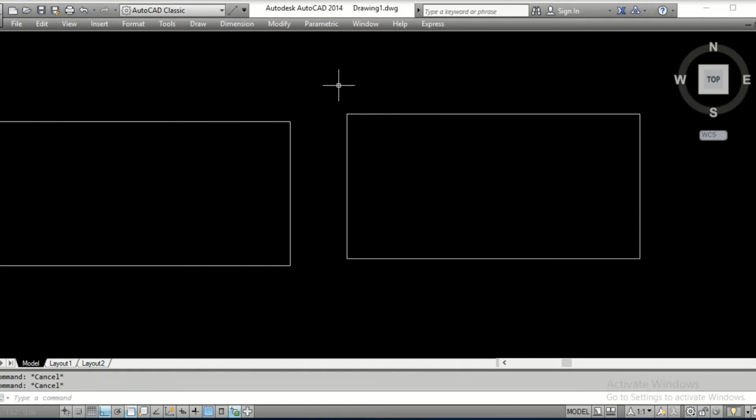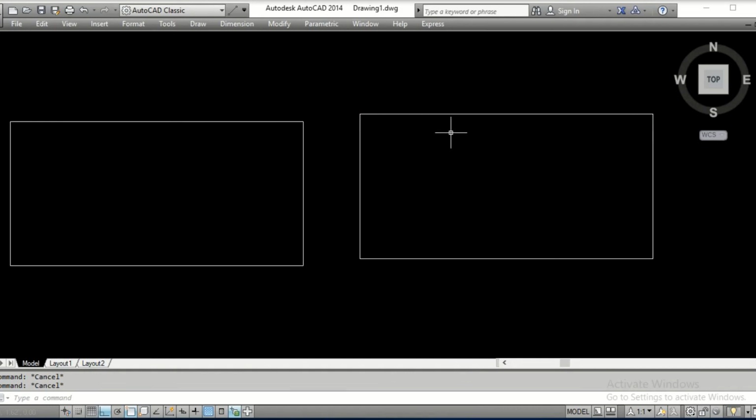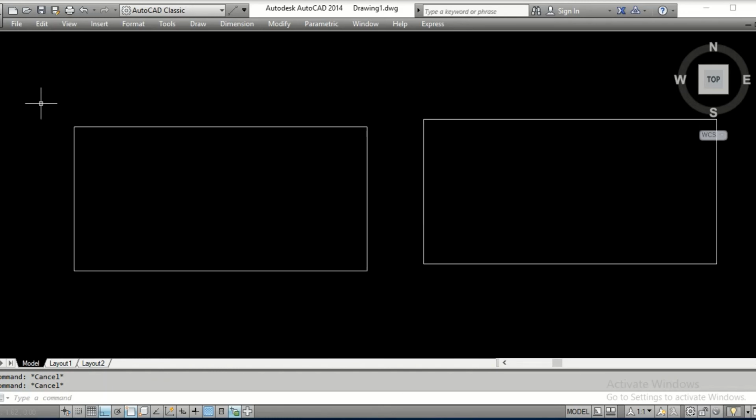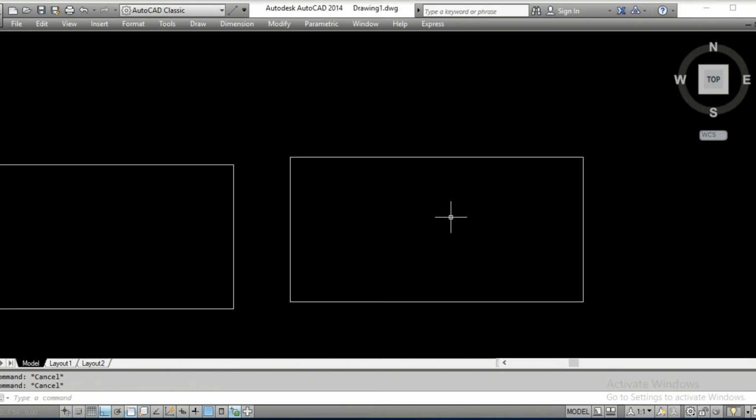So this is a purely 2D object. It can never be used in 3D modeling for any complicated drawings. But here you have one object which is very much perfect and it is a single entity. So this can be converted into lines, if so required, by using the explode command, EXPLODE. Just select this, press enter, gone. It becomes multiple entities. So then what about this one? Can't it be converted into a single entity?